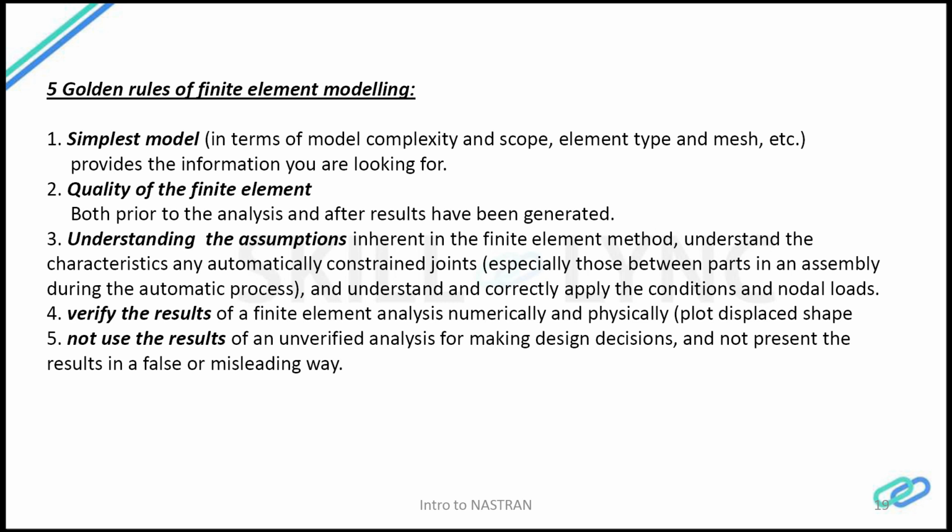There are some, I would coin them, golden rules of finite element modeling. One is simplifying the model: eliminate the complexity, and do an idealization that, if not accurate, is at least close enough to bring down the complexity of the model.